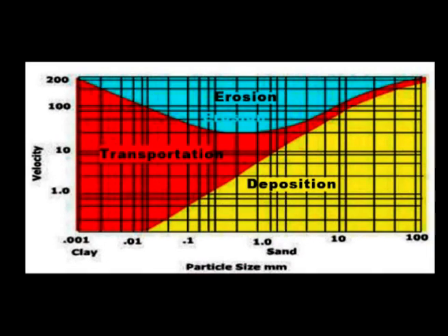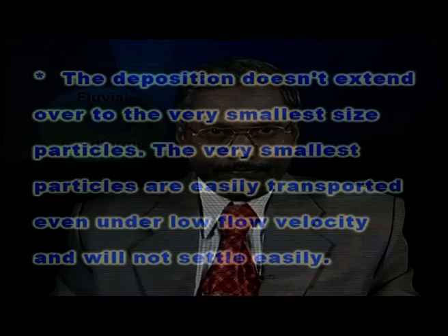Let us examine the minimum flow velocity for erosion. Clay gets transported at any velocity. When velocity is high, all materials get transported. At the other end of the spectrum, the largest particles like sand require high flow velocities to erode them. Similarly, larger sized materials are harder to transport due to their weight.